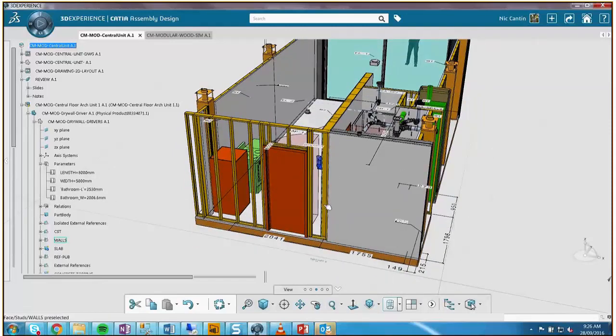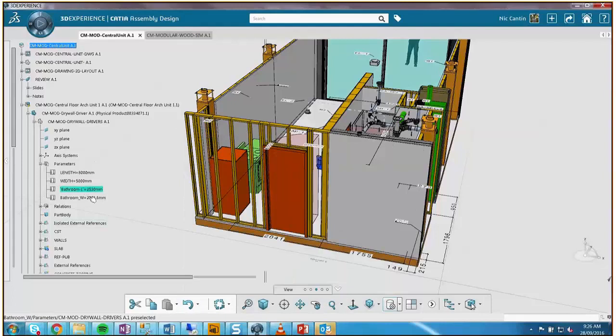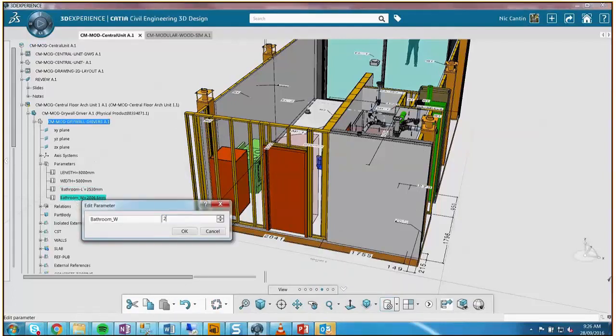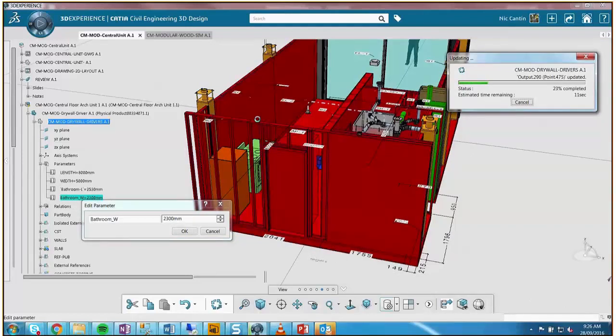So the next project, we're going to show at the end the iteration of this tool into more of a batch process. That's what we're doing, all the canning for this twisting tower with the drywalls as per the stud spacing and thickness of stud. And it's nice because the tool's built to have all that in custom, so you can just toggle back and forth the distance between studs and the thickness of the studs. So you can do it at the global level, or you can go in one by one and change it if needed. That's great.